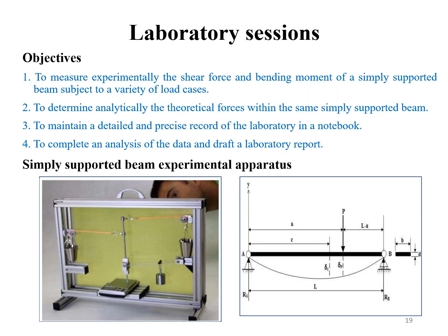Let's have a brief introduction for the lab sessions. A three-dimensional beam is tested under different loadings, and load, deflection and reactions are measured. These derived results are compared to the results from analysis using a two-dimensional model of the beam. Thus, a comparison can be made between the model of the beam and the performance of the actual beam, and therefore the validity of some of the assumptions made in forming the model can be examined.